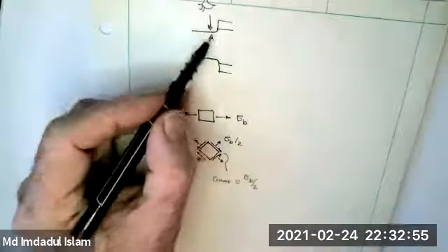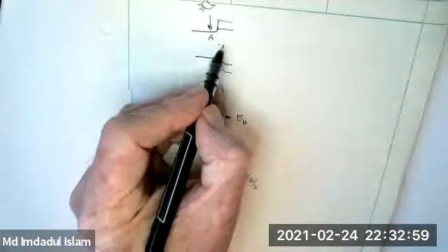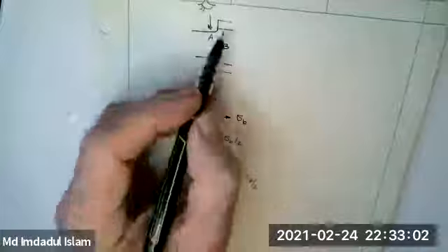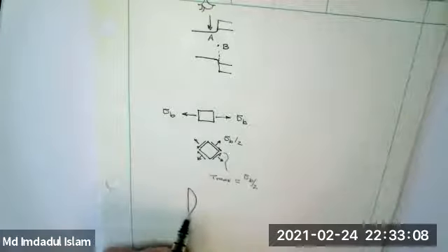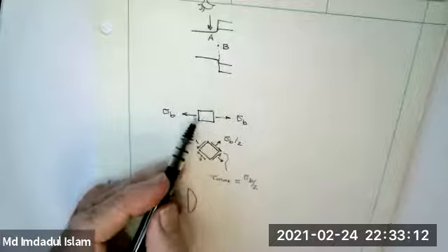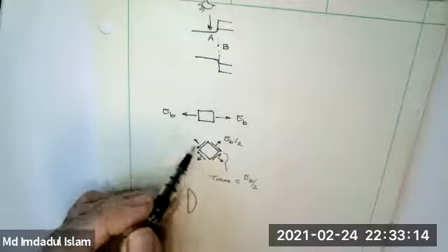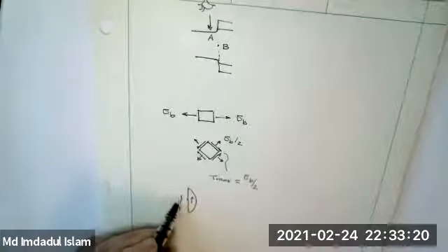Now there is a distribution of the shear stress through this section, and its maximum is at B. If I cut through that section, that shear stress distribution looks like this. It goes to 0 on the outside. So when it's lined up in this direction, it is 0. You have to get on 45 degrees to get a shear stress. So this is not an accident. It goes to 0. But here's its maximum at B.